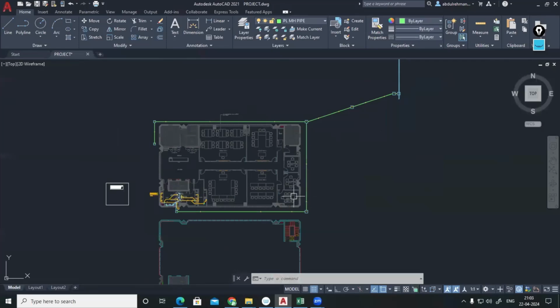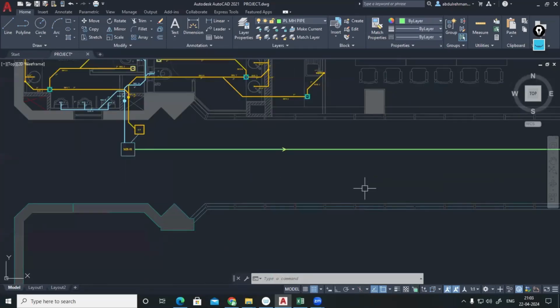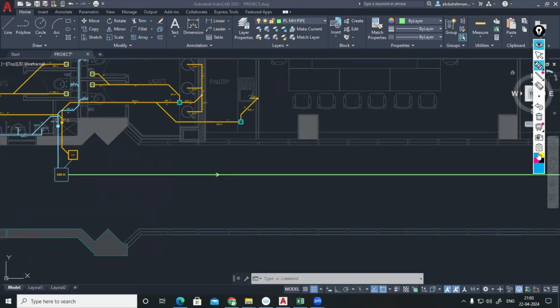Okay, now this external drainage, for every manhole we have to find the cover level. For example, if this is your building, from the building we'll be having ground level. Normally the ground level we'll be marking as 0.0 meter only. Any value means reference point 0.